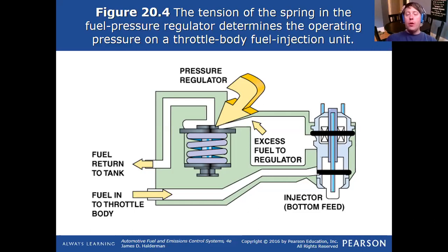Typically with heavier load, your throttle plate's wider, trying to accelerate, you'll see fuel pressure climb by a few PSI. The fuel pressure regulator's job is to maintain that consistent fuel pressure at all times. The pump can typically push out multiple times the pressure. So if the pressure regulator is set at 50 psi, the pump may be able to put out 100, 150 psi. It's limited by the fuel pressure regulator.